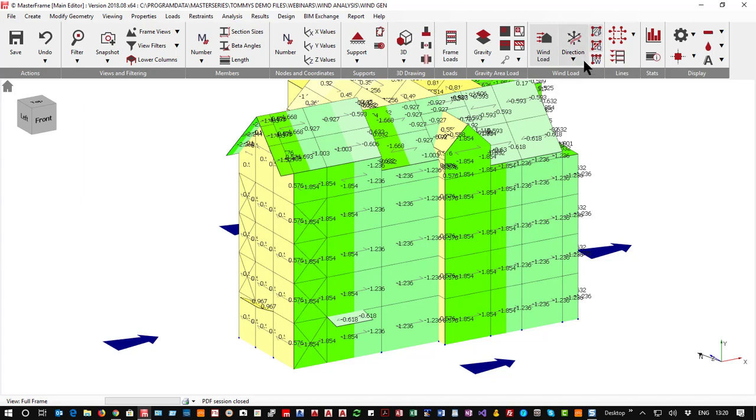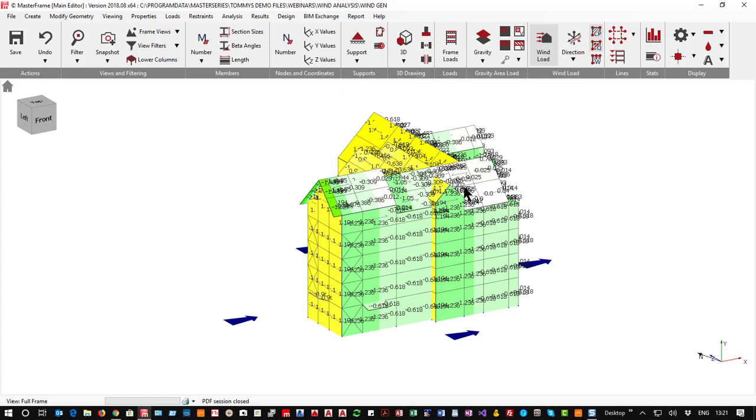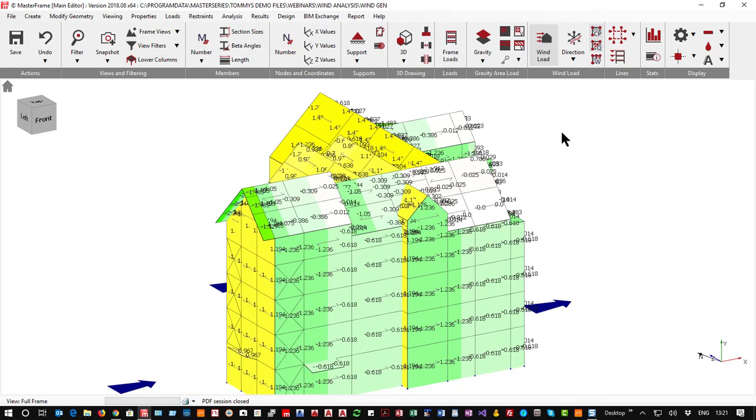And then you will see also when I walk through to the S1, these values here should suddenly drop down and these increase because the suction on the inside is putting this in, whereas that's been pulled out. This has been pushed in and pushed out, so they're countering each other, and you can see some of them come down to negative. So there we have all the different wind pressures on the structure.